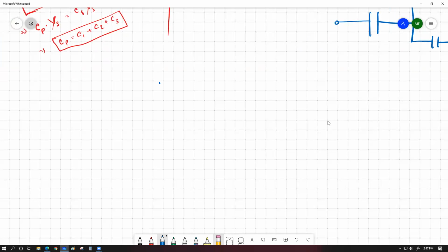Have a look. Whenever a capacitor is charged, say we have two plates over here of a capacitor. Here are the two connecting wires, and within this plate, let's say we have a piece of dielectric medium, which is the insulator medium, that is responsible for the atomic level deformation of the electron shells. The negative charge center and the positive charge center, which is the nucleus, are not perfectly overlapping each other's position, so we have a bit of distortion, and that distortion is by which a capacitor stores energy.